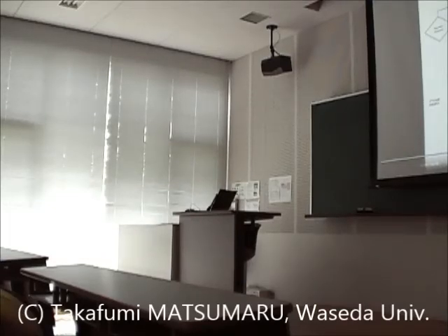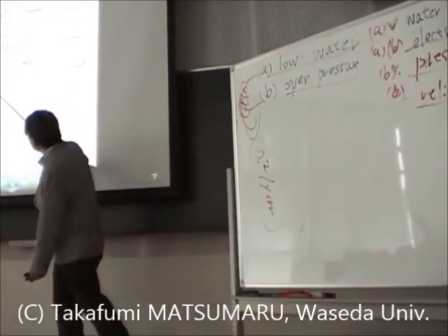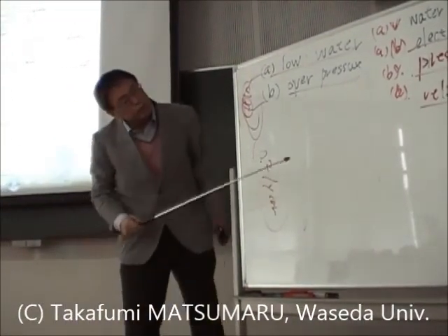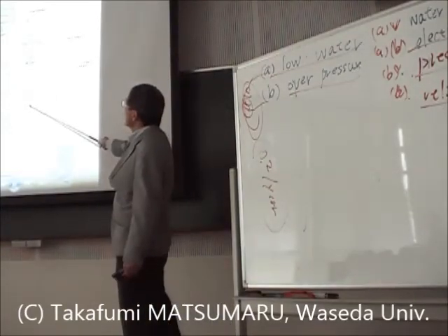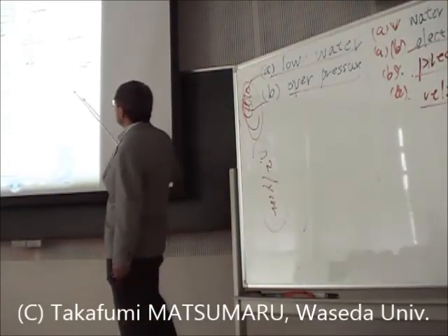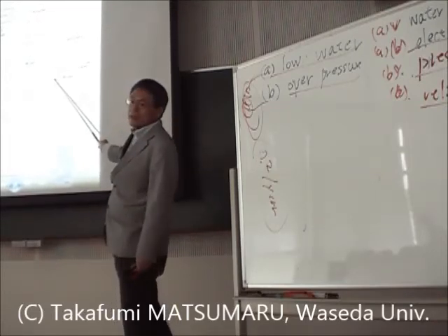So that is an OR gate because again it is either the level detector failure or an electrical fault. So the overpressure condition B, there's actually three conditions. It could be due to the electrical fault or the pressure switch or the relief valve. And again, because it could be either of these, that is also an OR gate. So that is what your fault tree should look like.